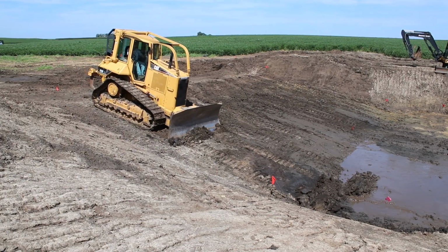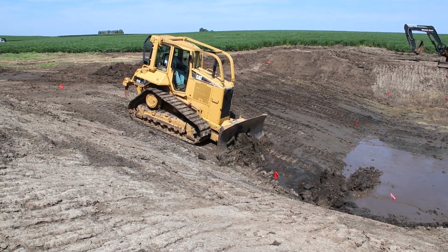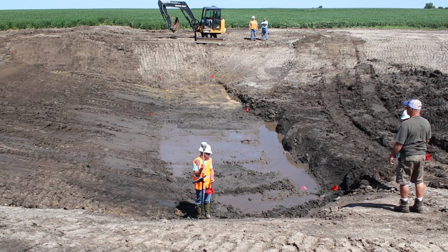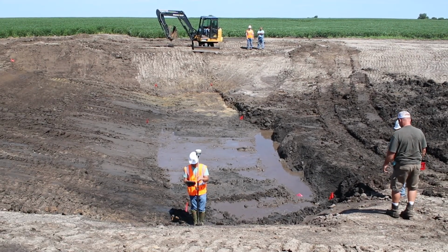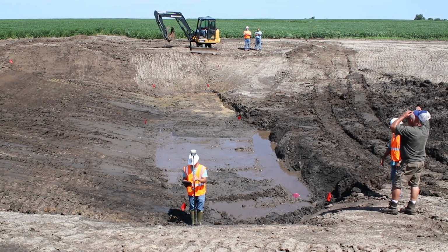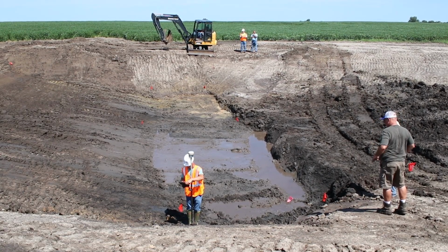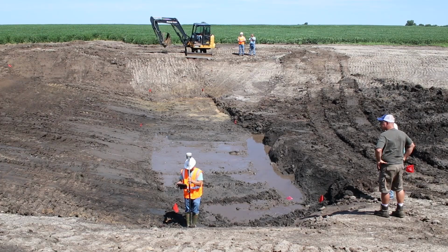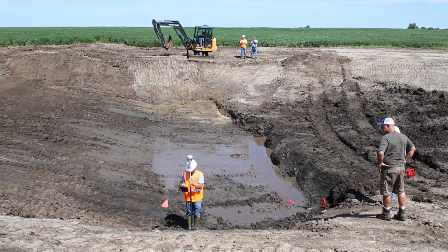With the inlet and the outlet apron elevations established, the dozer could now grade the chute slope before moving on to the side slopes. The engineer worked closely with the contractor throughout the process of installing the tied concrete block mat rolls. Here you see the engineer checking elevations and the layout of the outlet apron before the contractor moves forward. Continuous elevation and grade checks, along with fluid communication with the contractors, was the key to having a smooth installation process.